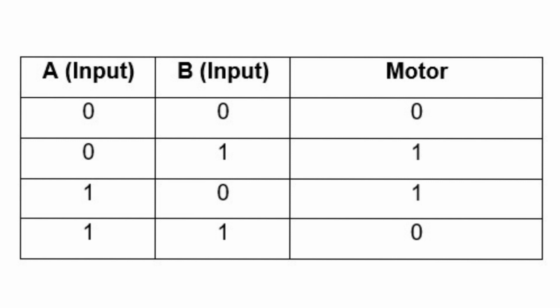We can see in the table that the output for this part is the same as that of the first part. This is because they both make use of the 7486 quadruple 2-input exclusive OR gate. Thus, an output of 1 is observed if both inputs are not alike and 0 if they are alike.